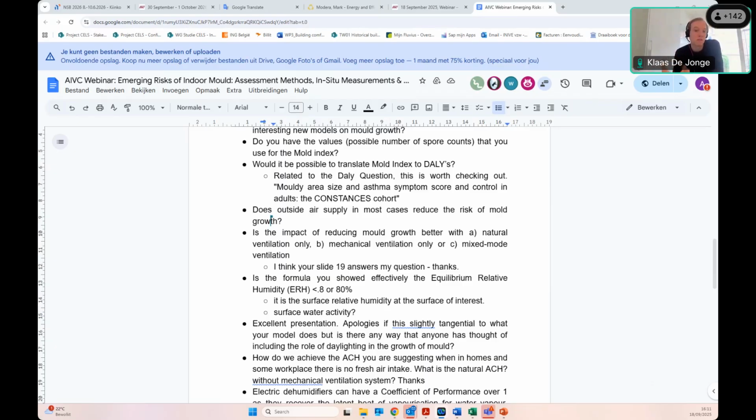And once you have a source rate of mold spores, based on the index, it's a matter of estimating how much area you have at the low thermal bridge levels in the space, figuring out which index you have, which source strength of mold spores you need to attach to that, and then, assuming that everything mixes in the space, you get an exposure profile of people to those mold spores. So it's not a direct correlation, but I think it's only a small step to add it as a contaminant in the air model, of course.